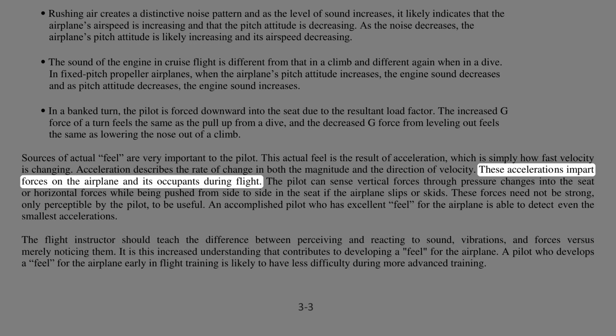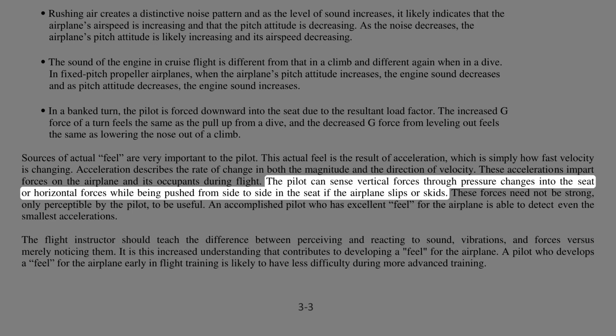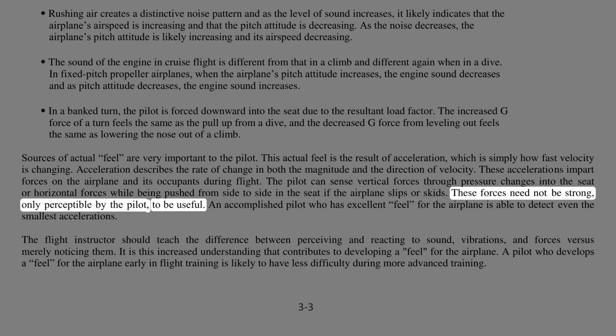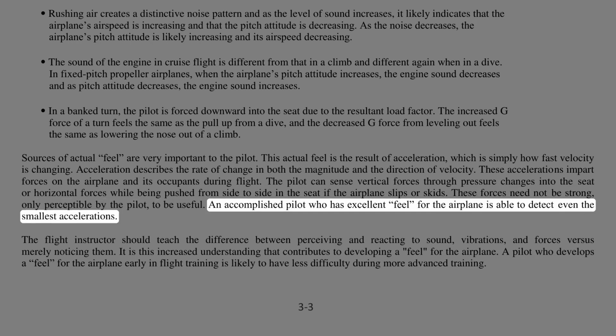These accelerations impart forces on the airplane and its occupants during flight. The pilot can sense vertical forces through pressure changes into the seat or horizontal forces while being pushed from side to side in the seat if the airplane slips or skids. These forces need not be strong, only perceptible by the pilot, to be useful. An accomplished pilot who has excellent feel for the airplane is able to detect even the smallest accelerations.